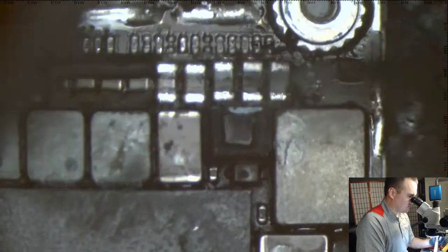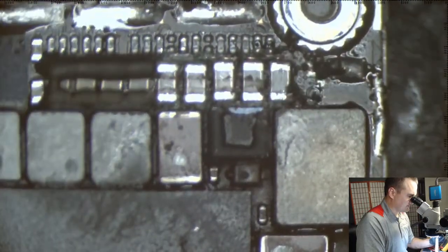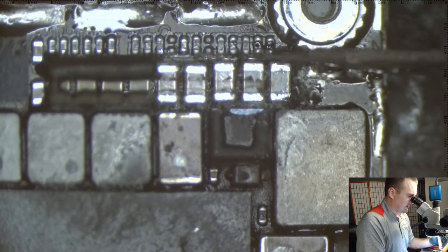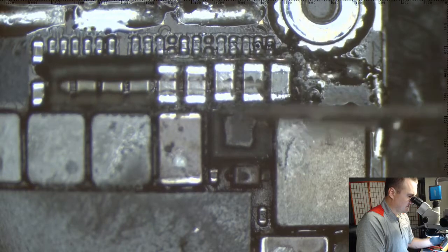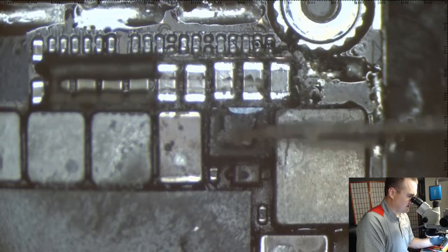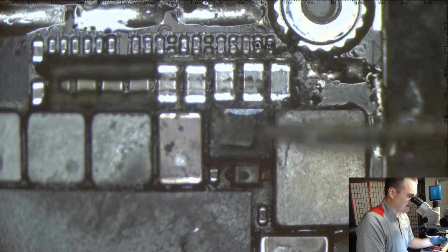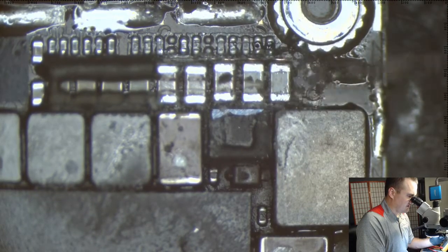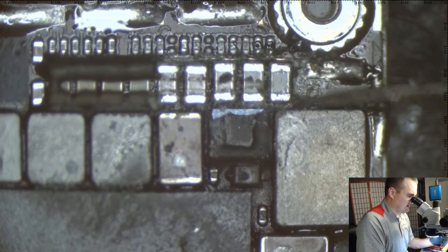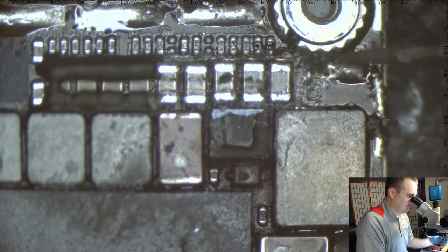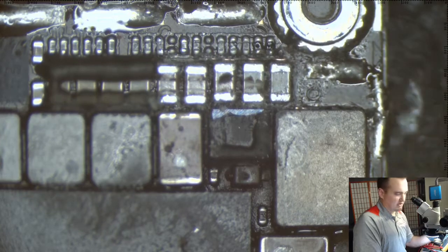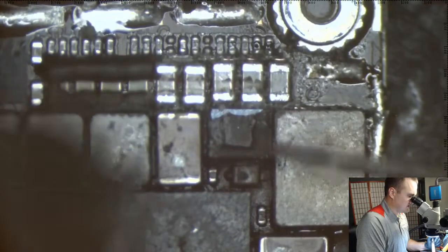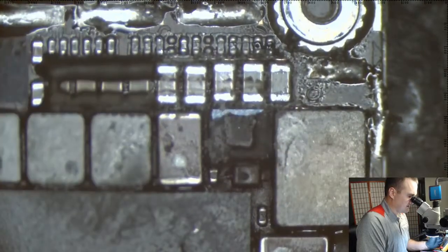It's always one of these three capacitors. They're all in parallel, backlight anode capacitors. And it's one of the three. So really at this point, what you really ought to do, you could inject voltage to the line and throw some freeze spray on it or throw some alcohol on it and see which one heats up first, because a short is always going to produce heat.